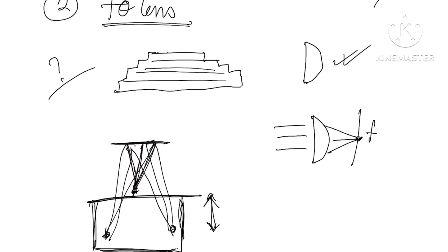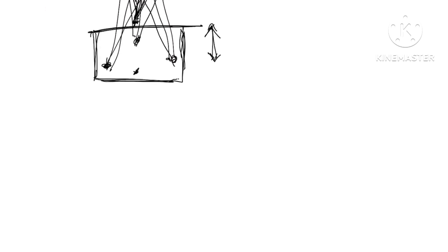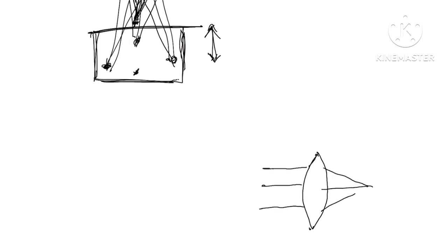And if we are working at the focused position, then at this point and this point, and whether the laser is coming at this point or this point, all these points should have the focus of the laser beam. We all know that if this is a normal lens, the normal working principle says that if this is a parallel beam, the lens will focus it at its focus position. This is the focus of this particular lens L1. This is F1 and this distance is F1.